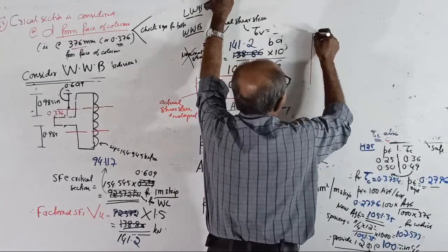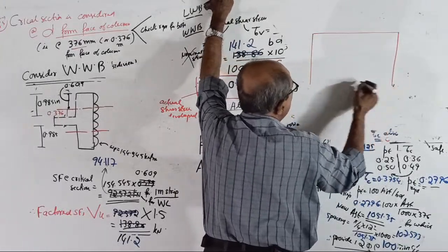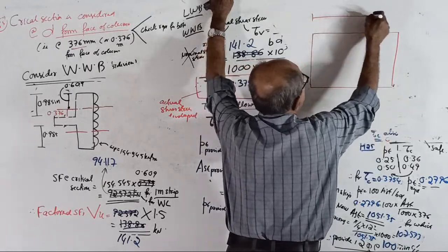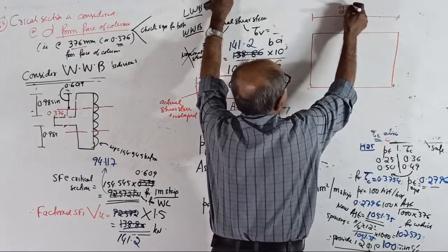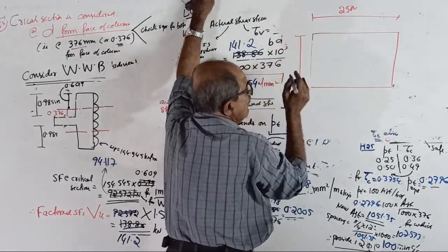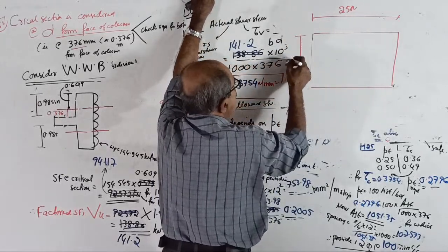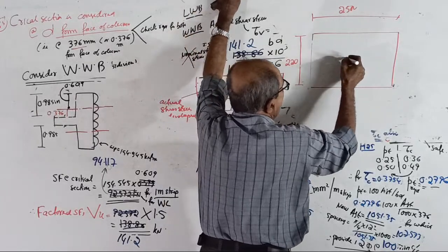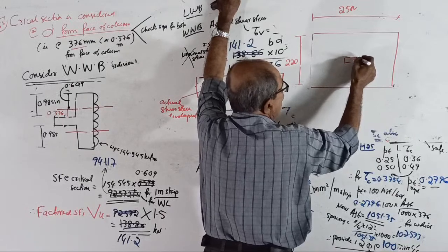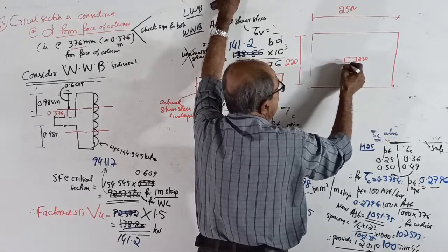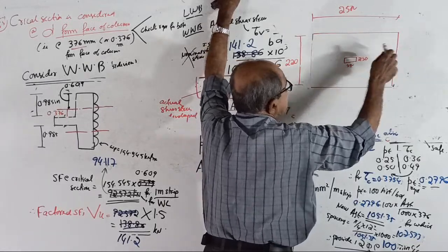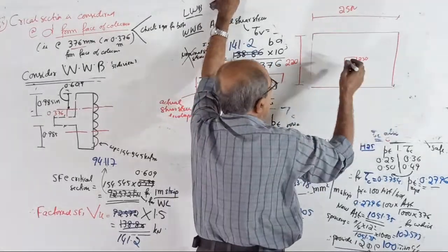Red I will write, no space here. Red color came, I use red color. Okay, right here. This is 2500. Usually in the final drawing, always write millimeter. 2200. Column comes here this way. That is actually not required. 230 by 550. You show, see, this is lengthwise steel. So many bars will come, not required.